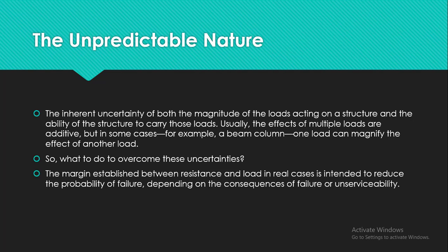In the best of cases, the combined effect of multiple loads related to a particular limit state or failure mode can be described with a mathematical probability density function. In addition, the structural limit state can be described by another mathematical probability density function. For this ideal case, the two probability density functions yield a mathematical relation for either the difference between or the ratio of the two means and the possibility that the load will exceed the resistance.